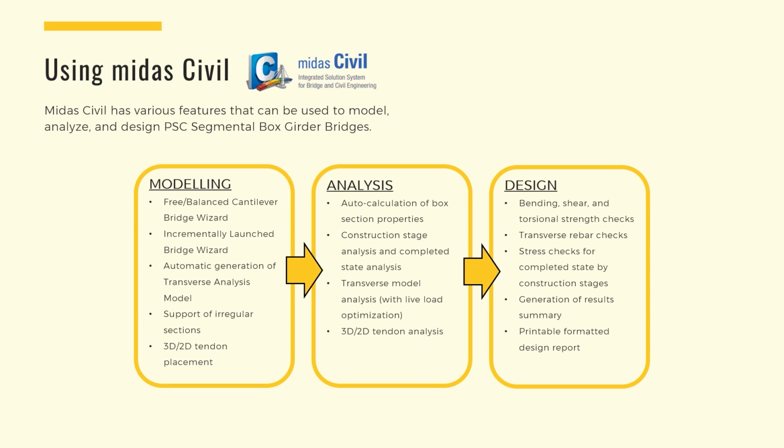In designing our PSC segmental box girder bridges, there are a number of MIDAS Civil features that we can take advantage of. To name a few, for modeling, we have our various bridge wizards. There is also support for irregular sections and the ability to place tendons in 3D or in 2D. For the analysis side, the section properties of the boxes are auto-calculated.